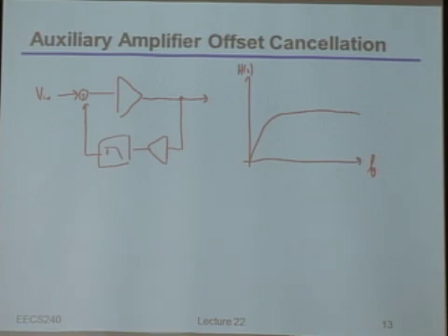1, right? Okay, so that means that, by the way, you could indeed do that. It would just be a gain of 1. But as we had said with the input offset cancellation, the net gain in this feedback loop will just be set by the gain of the amplifier in terms of canceling that offset. And so if your amplifier gain is high but not high enough, you won't necessarily track that offset out perfectly.